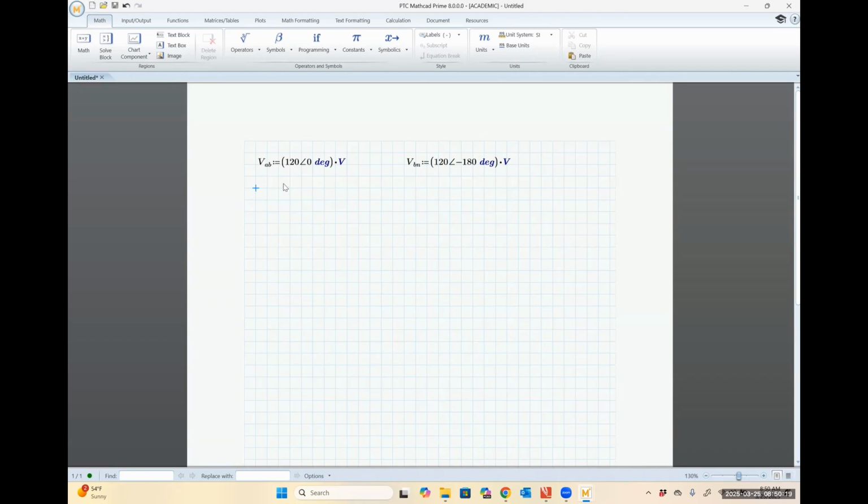Now I'm going to set up my impedances, right? So I have an impedance of Z wire, and I think that was 0.1 plus, let me go back here real quick and look, J 0.08. So I'm going to enter that in as 0.08 J. I need to put the J afterwards, otherwise it is not going to correctly interpret that. Let me just show you real quick here.